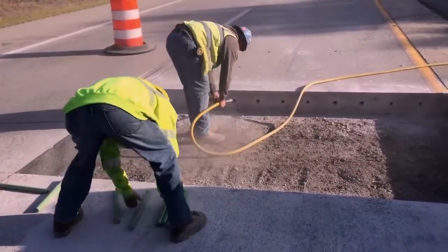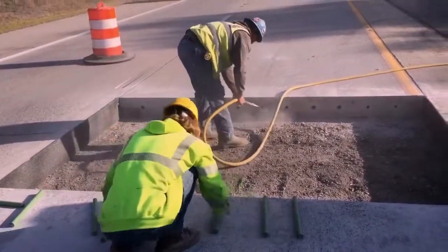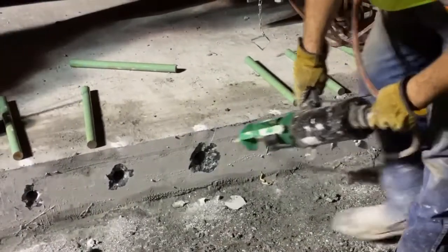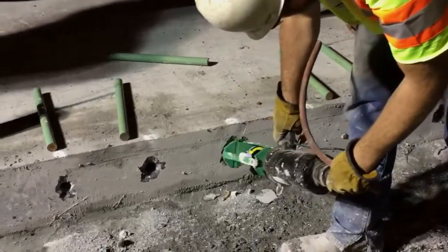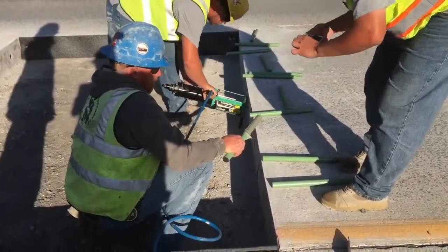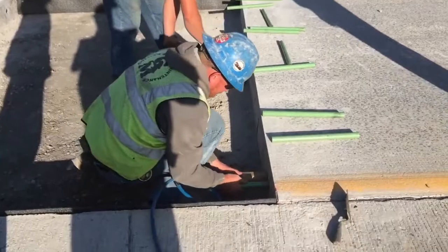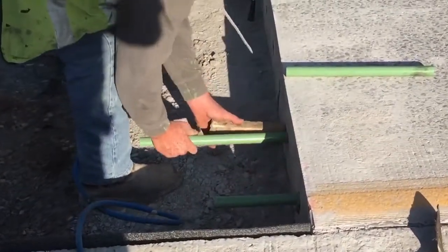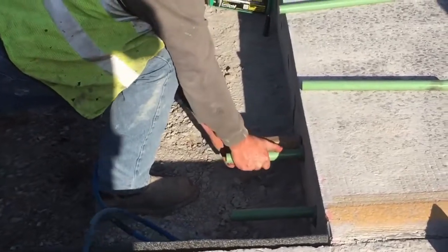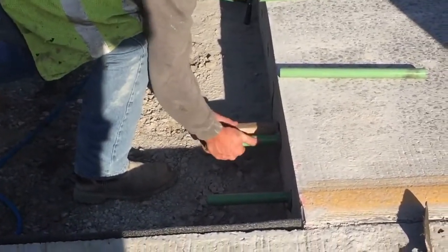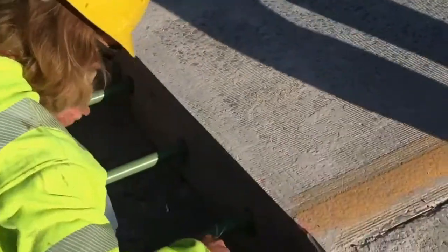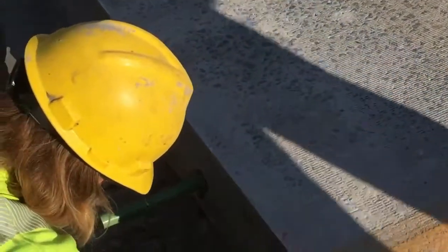Dowel bar placement. Blow debris and dust from holes using compressed air. Place Bulletin 15 approved anchoring material in rear of dowel holes. Insert dowel into the hole and rotate 3 to 5 complete rotations to properly purge air voids and obtain uniform coating of anchoring material that should come to the front face of the patch joint. This is a very important step. Trowel any excess anchoring material flush with joint face.